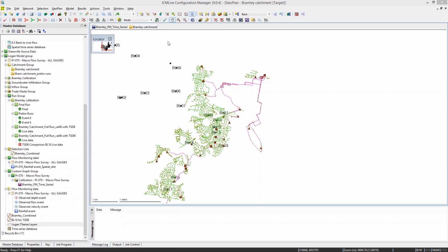So let's dive into a couple of tips on the initial model setup. When we're talking about calibration, you've got your hydraulic model, which is the below ground assets, the physical model, and then your above ground part of the model, which is really your hydrology. Most water authorities would already have a model set up, and the accuracy of the asset data behind that model, in my experience, can be patchy. We have some of our models built on drawings that date back to the 70s. Some of it's very recent as-constructed data, and even the very recent data can have some issues with it.